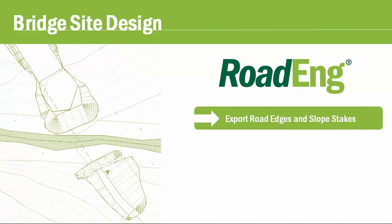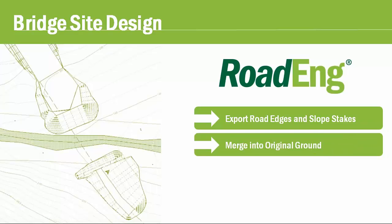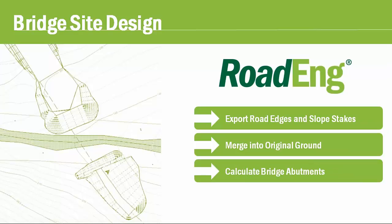So, bridge site design, what Jack is going to show you today. He's going to open up an original design in location module, export the road edges and the slope stakes, merge it into the original ground back in our terrain module. From there, he's going to calculate the bridge abutments, and then after that, design the retaining wall components.